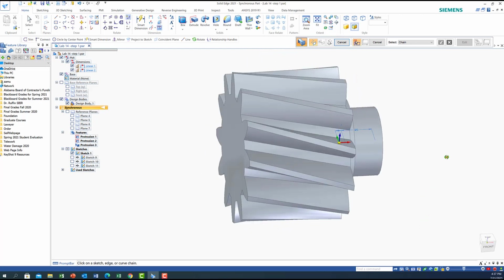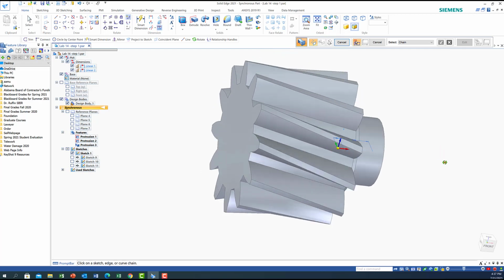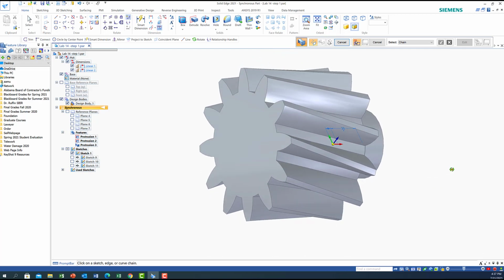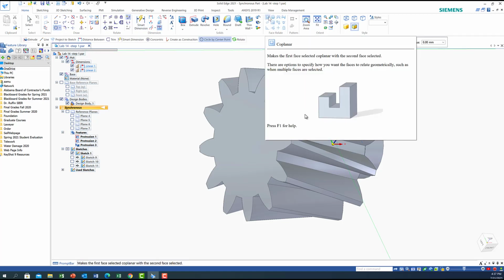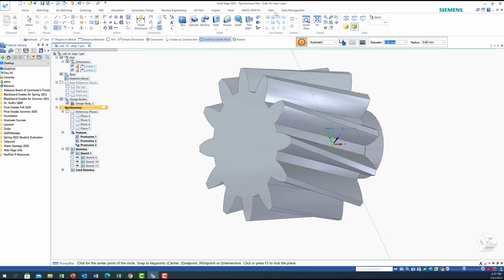So as you can see, this will become the helical gear and the tooth. Okay, now we'll do the same thing. First, let's go to this side here. I'm gonna get the circle by center, and we're gonna start with the inside one, which will be the 60 and the 45. So okay, we're gonna say okay, 60.